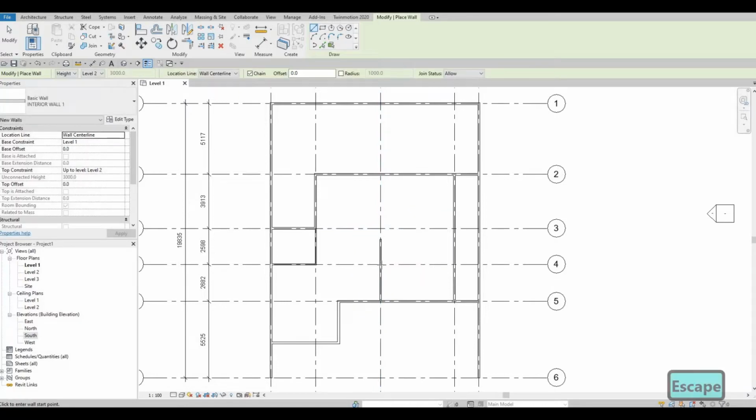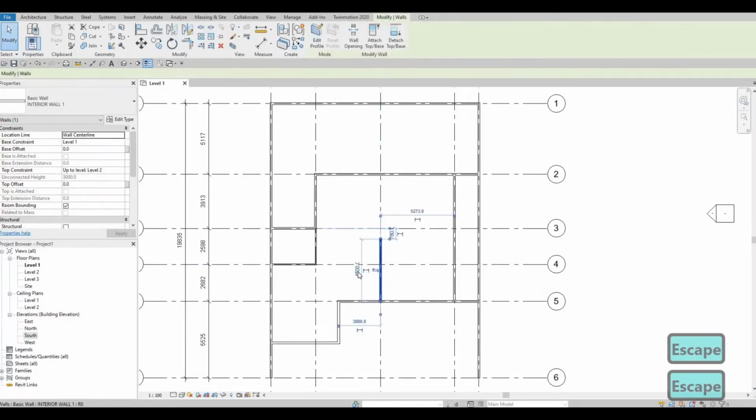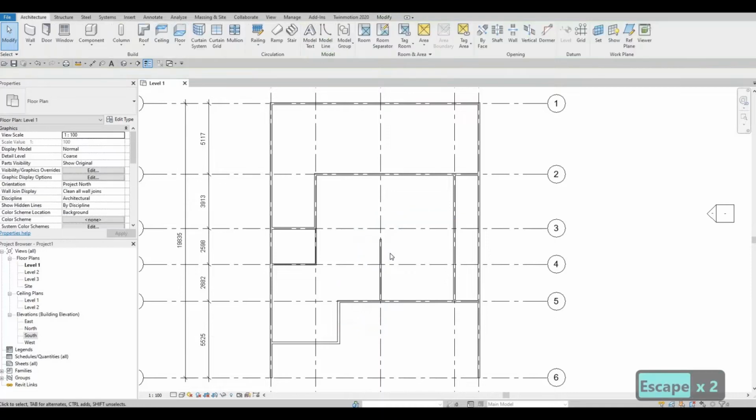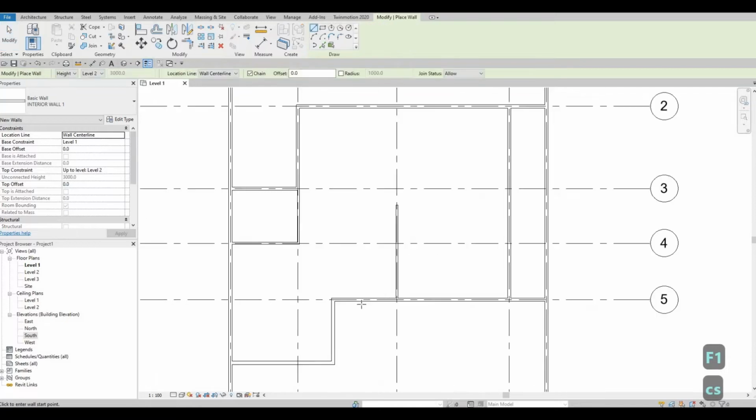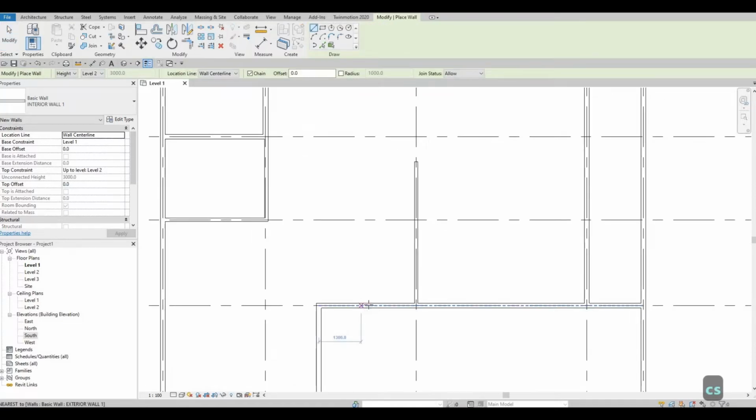So right there, let's put it at 4500, which is exactly what I did. So just click right here and then add it 4500. So that will be good. And then let's add in a room right here, which will be the powder room. I'm just gonna give it a gap of around 1200 for the main entrance door.